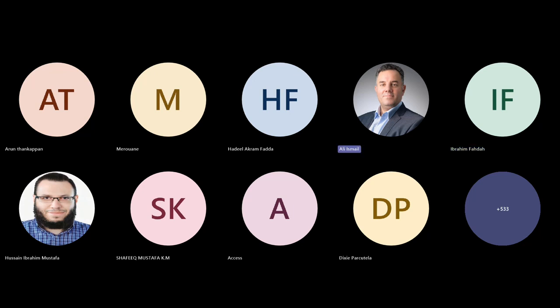Regarding the question about overriding internal walls, there is an attribute for all walls indicating if the wall is external or internal, so no need to override it. You just have to set this parameter, internal or external.